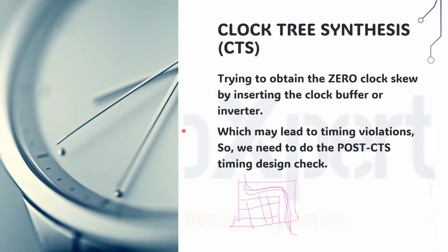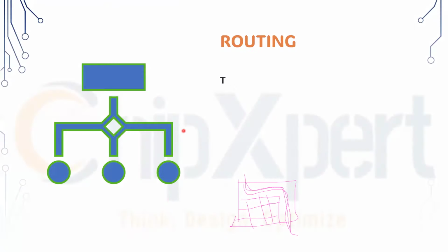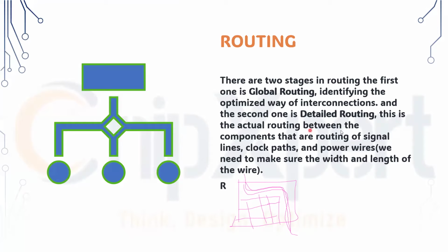Once we are done with the clock tree, we go to routing. What is routing? Routing is where you connect each and every connection from gate to gate without any shorts or spacing violations. There should be some standard for the spacing of each net side by side. They are properly going, but they don't have any insulation for the side by side wire, right?